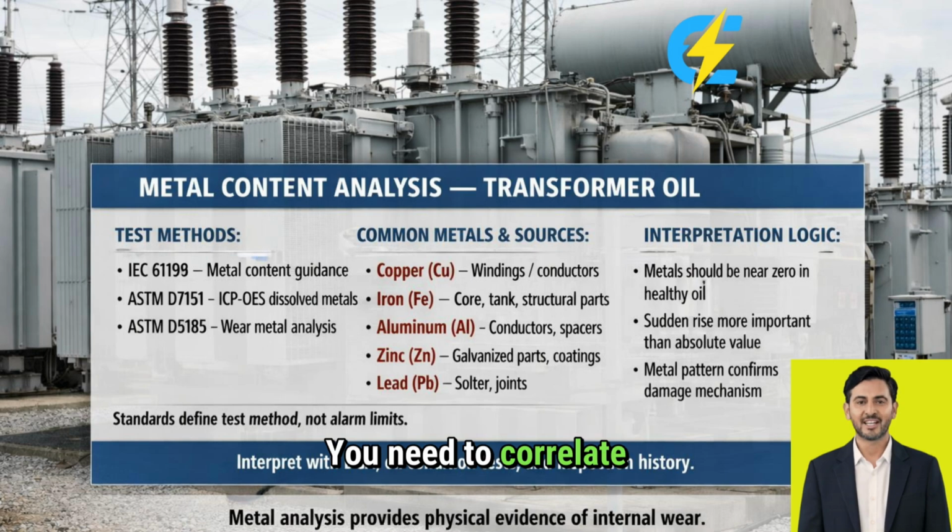You need to correlate metal findings with oil chemistry results. High copper with rising acidity and moisture suggests active corrosive attack. High iron with normal oil chemistry might indicate mechanical wear rather than chemical corrosion. The story emerges when you look at all the data together.